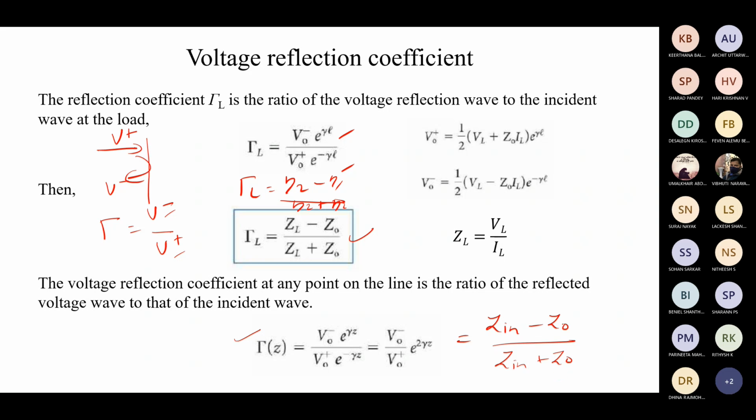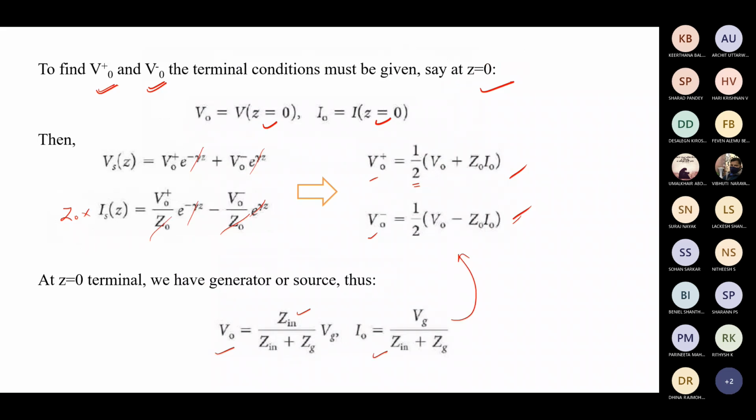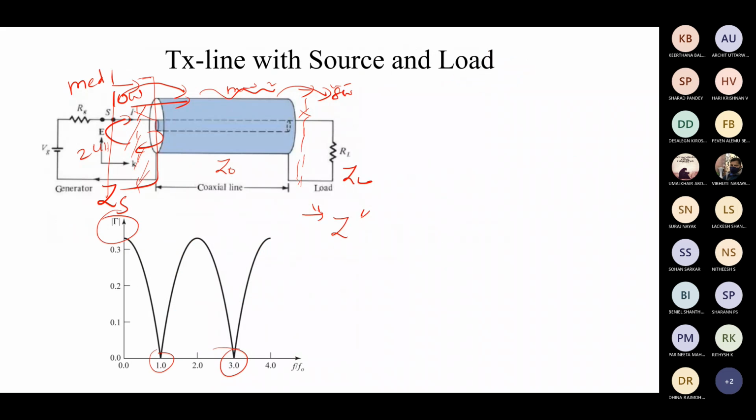So that's all. We got the load side reflection coefficient, and the input, we often refer to this value as gamma in, which is nothing but the input reflection coefficient. Okay. So by this we have defined the very important problem we thought of describing. So at this source side, people usually do like this. We have a transmission line whose alpha, beta, Z0 is known, and this is the starting point, 0, and this is the end point, and here we have connected a load.